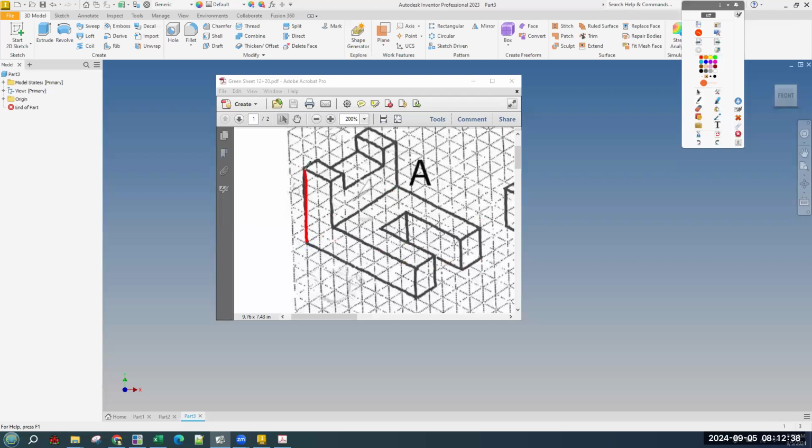And our general path is going to be: we'll do the full block, that the whole thing could fit in the maximum dimension in all 3 dimensions, which would be a block this size. And then there will be 3 different cuts. One is making it an L shape, cutting across. Then on the top of that L, we're going to make this rectangle that is actually sort of floating front to back, extrude that down. And then the last one is going to be make this rectangle here that's 1 by 3 with an offset and extrude it over.